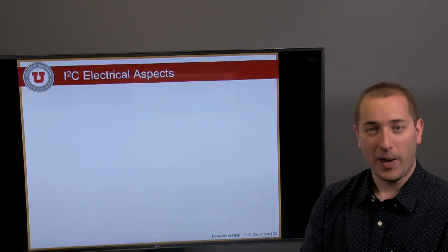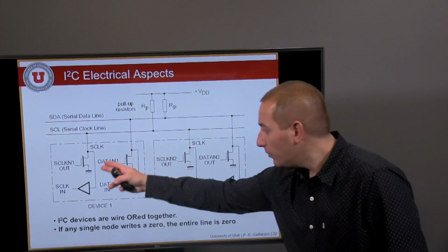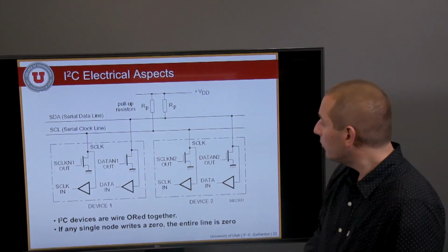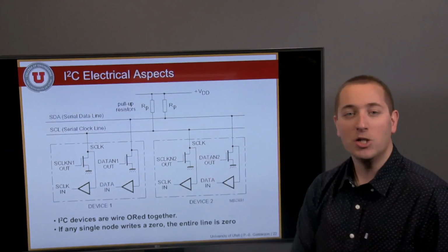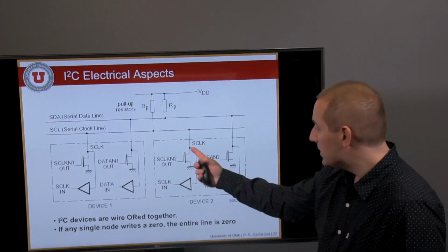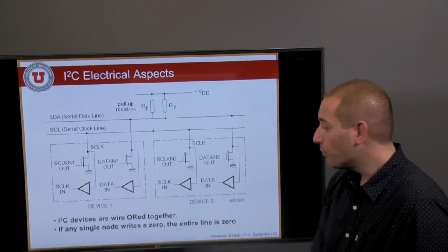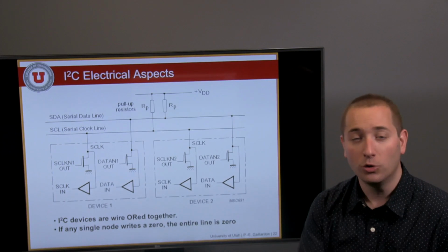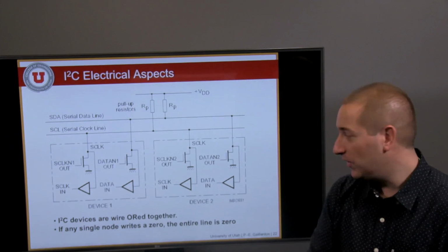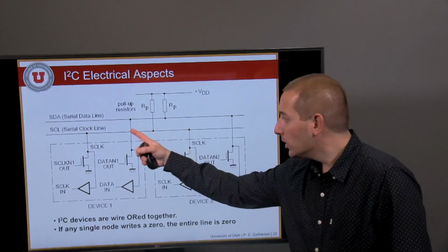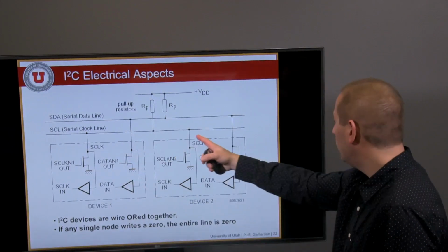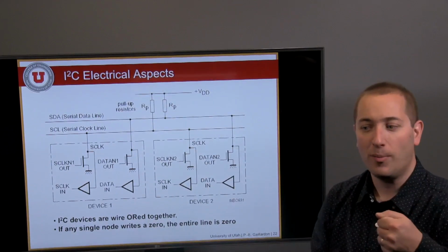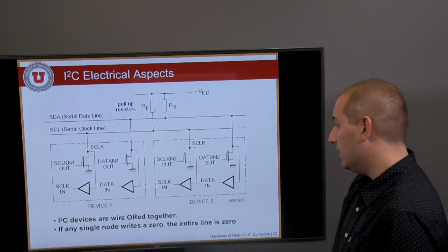If we look at the electrical aspects, as I said, every single package will implement an open drain type of output. In an open drain, let me remind you that only a transistor with the open drain will be connected to the output, which allows this specific transistor to only pull down the node or leave it floating into the Z state. And that way, you will be able to pair several devices on a single and unique line, coupled with a pull-up resistor to make sure you apply a proper signal up to VDD.